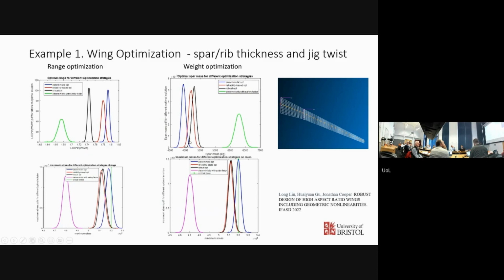So this is a 1.5 safety factor, and there's also a 1.5 safety factor there on the maximum stress. So there's a big gap there. What that is indicating, just from this study, is that by taking, say, a 50% safety factor, you are making a rather inefficient structure.